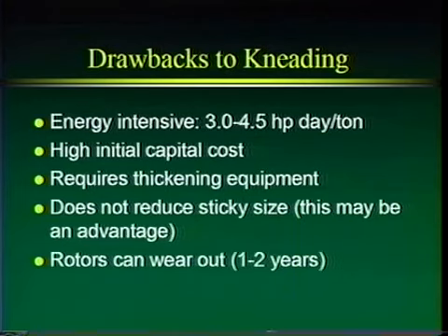Kneading doesn't typically reduce sticky size, and this may be an advantage because sometimes it's better to have the stickies large than small. If we have the stickies larger, it's easier to screen them, and screening is one of the more effective ways to remove stickies. So it does not reduce stickies.